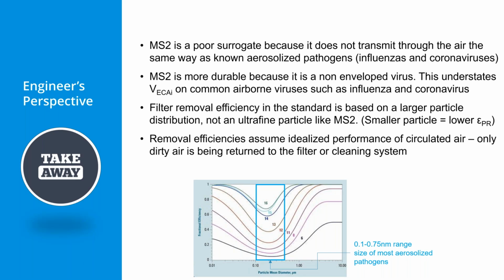That's a little bit of the commentary on this, but in general, what is interesting is you get a standard for all that actually applies, that can provide a background for everybody to start to step from. And as engineers understand this disconnect between MS2 and real viruses, and how filter efficiencies really work with these ultrafine particles that are not being tested on the filter, you can start to tweak your designs to even better systems and healthier, cleaner air than what the standard already is leveling us up to.